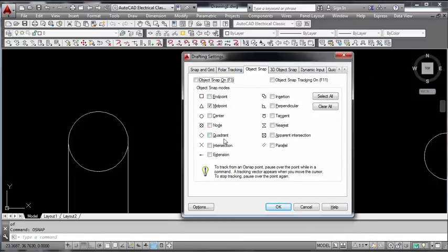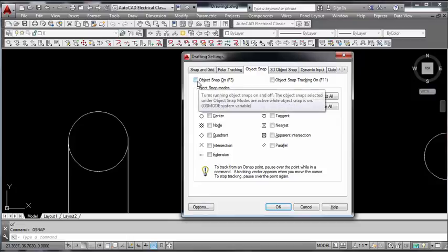See, here you might have noted one thing. In order to draw this 3-point circle, what I have done: circle, 3P, first point. Here I am typing END, okay? Enter. Next also I know I have to draw through the end of this line. Again I have to type END of, again I have to type END. This is a little time consuming, every time you have to type END.